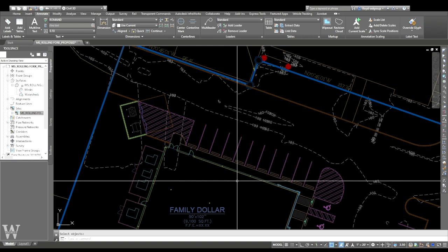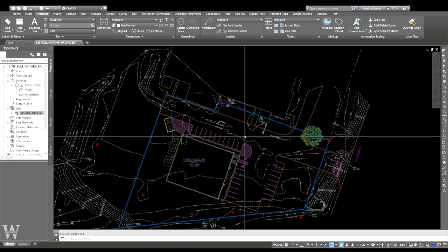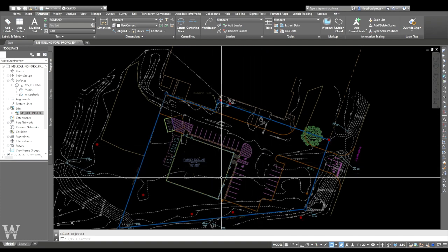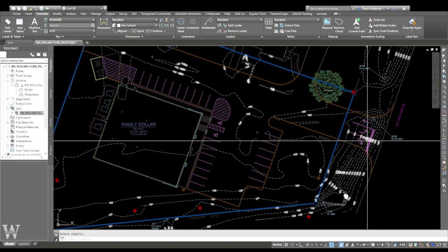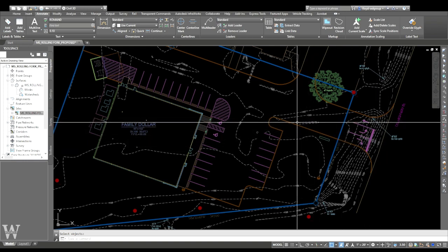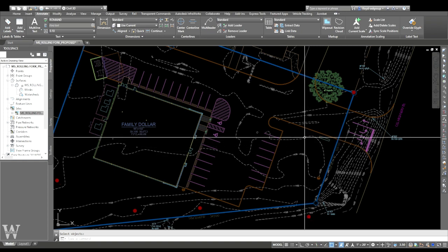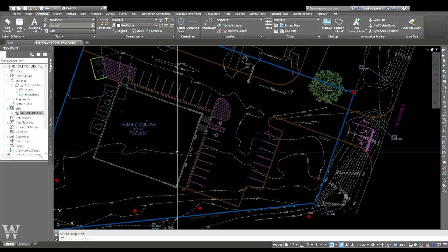I'm thinking that will probably work, because we don't have to. If I had to run my stormwater all the way around this building, which a lot of times I do, I'd have to be higher. So we're going to try 104 for our finished floor. That'll be a foot below here, so we'll be able to grade that driveway down and drop that water in here, which is great when DOT won't have anything going on to them, and that makes them happy campers.